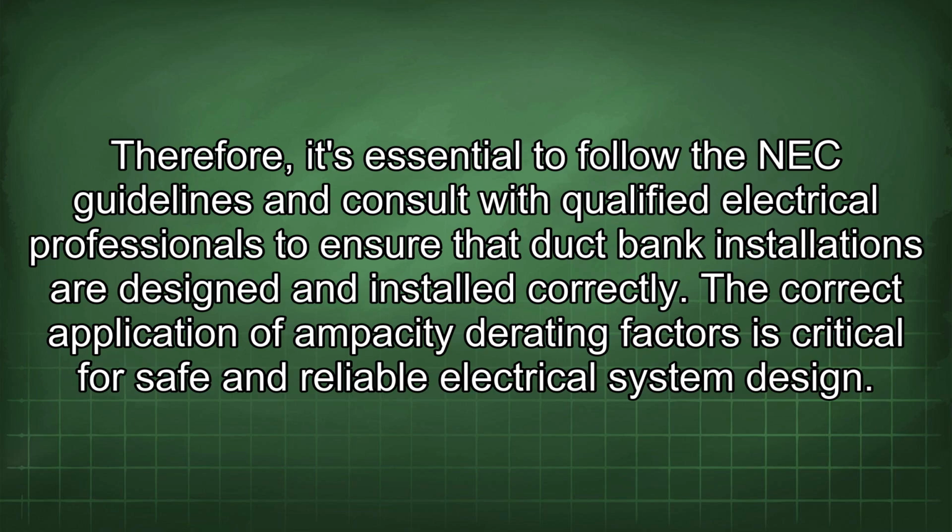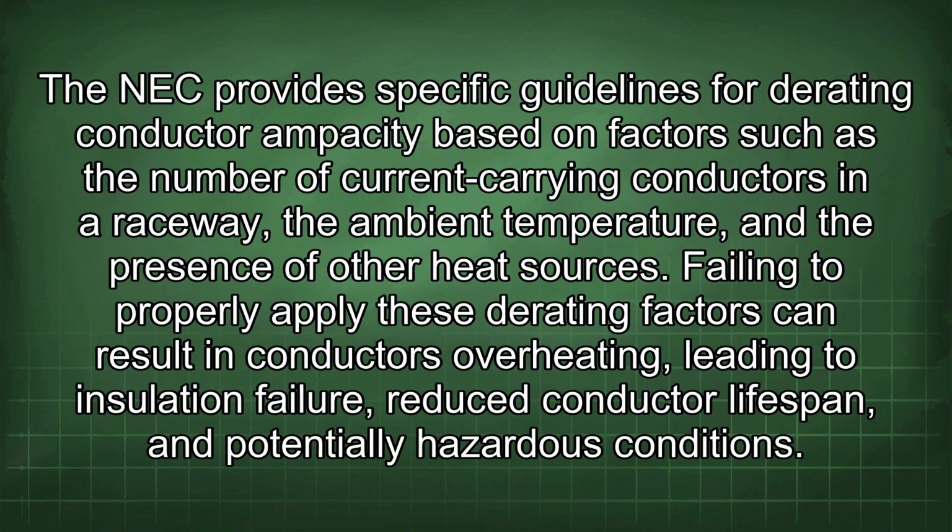The correct application of ampacity derating factors is critical for safe and reliable electrical system design. The NEC provides specific guidelines for derating conductor ampacity based on factors such as the number of current-carrying conductors in a raceway, the ambient temperature, and the presence of other heat sources. Failing to properly apply these derating factors can result in conductors overheating, leading to insulation failure, reduced conductor lifespan, and